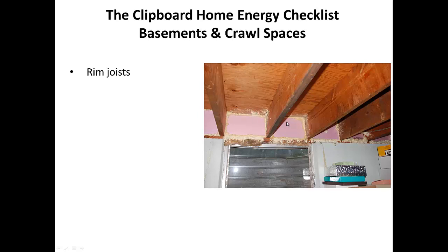So this is a great way to reduce both air infiltration, which is the movement of air through cracks, and to stop those conduction losses, which is the movement of heat through a material, with this rigid insulation.